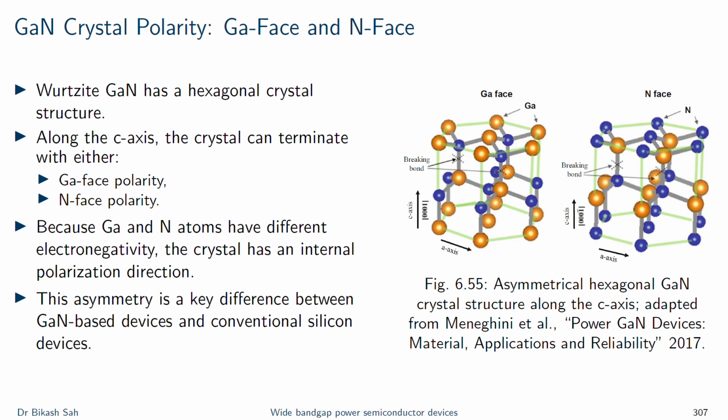For silicon devices, we usually know that the doping is critically important, but for GaN HEMT, we must understand that the polarity and the polarization are the primary thing, because the conducting channel itself can be created by the crystal and heterostructure physics that we have to understand.